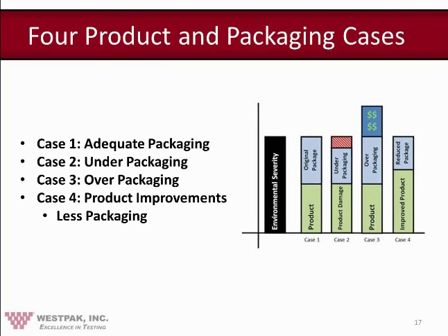And the last case is when you actually determine the exact fragility of your product, and you know that it breaks at a certain level, let's just say 40 Gs, and you tell yourself, this level is way too low. Let's put a little more money into this product, make it more robust, and cut costs and cut the packaging down. So if that's the case, a lot of things happen. First thing that happens is that your customer gets a better product. And then a couple other byproducts are that you use less material in packaging, and finally, you have less transportation costs in the supply chain as well. So case 4 is definitely the go-to case, at least for these packaging cases.